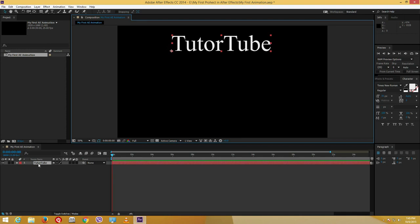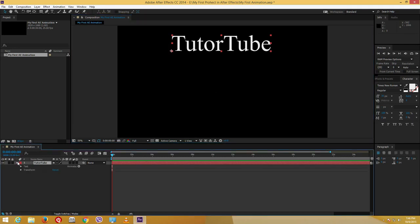And as you can see, this is what 2 seconds is like. Okay, so I want 2 seconds of animation. I want this animation to start from here and end at 2 seconds. So I'm going to go over here at the left corner, which looks like a little triangle. I'm going to click that, and it expands the settings of this text. So you can go under the transform menu, and you can see a lot of